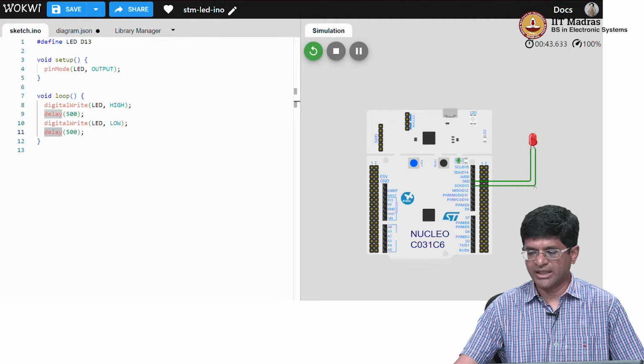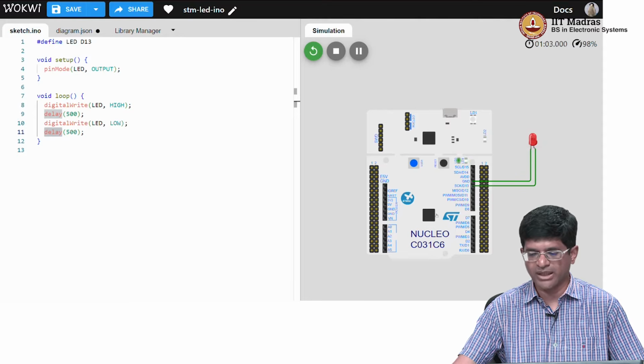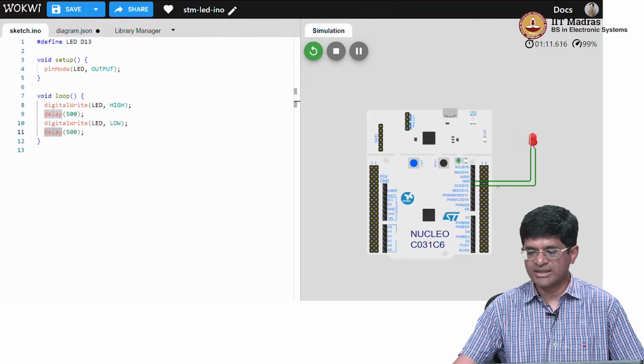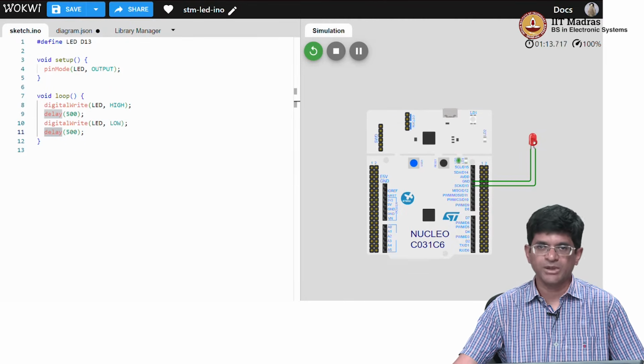So what ends up happening as a result anyway in this case is, you can see that this seems to be blinking with a time period of 1 second. Now interestingly, you will also notice that there is yet another LED out here that is also blinking, and it turns out that this pin which is connected to D13 over here is also, there is another wire running from this microcontroller to that particular pin out there, right, which in turn makes the LED glow. So you can see that we have accomplished what we wanted.